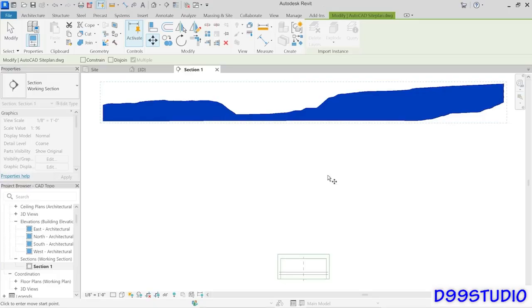So it's a really good idea if you can take a look at the CAD file and see what the contours are. I don't remember exactly, so I'm going to do it in 2 steps. I'm going to start anywhere here. I'm going to pull it straight down, and the contours are measured. This is an imperial file. Okay, so we're going to use imperial units here, even if you're working in metric. But the contours are at about 780 feet above sea level. So what I'm going to do is take my best guess here, and I'm going to use 780 feet.